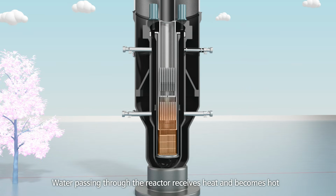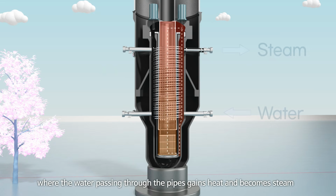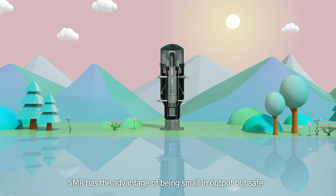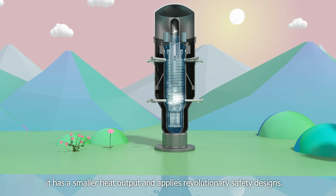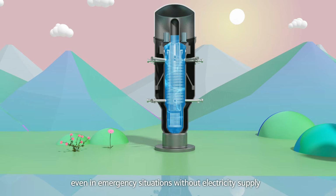Water passing through the reactor receives heat and becomes hot. This hot water is sent to the steam generator using a pump, where the water passing through the pipes gains heat and becomes steam. This steam then rotates the turbine to produce electricity. SMR has the advantage of being small in output but safe. Compared to large-scale nuclear power plants, it has a smaller heat output and applies revolutionary safety designs, allowing it to safely cool down the reactor even in emergency situations without electricity supply.